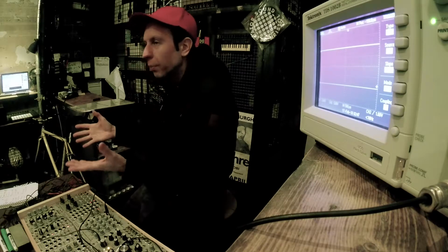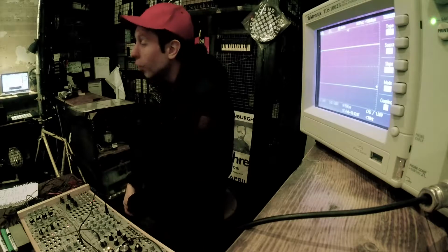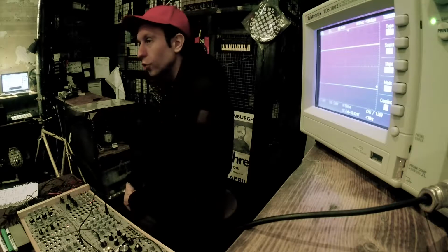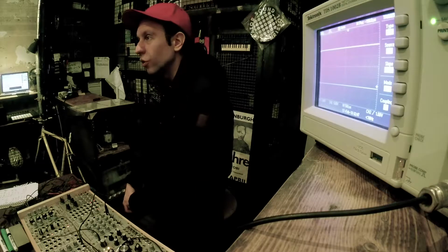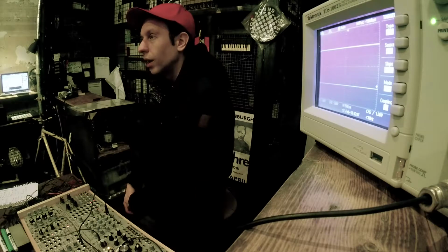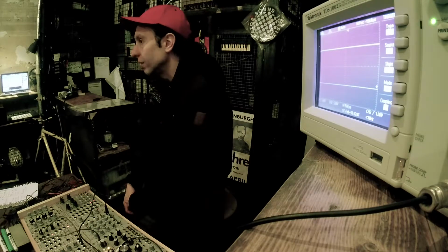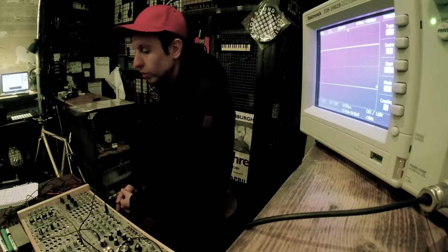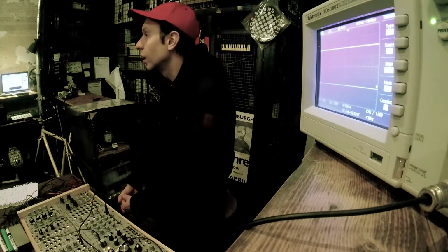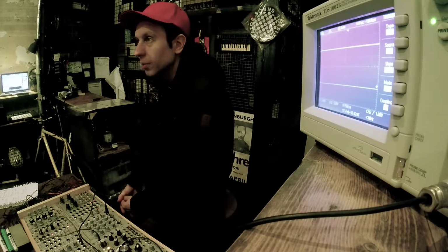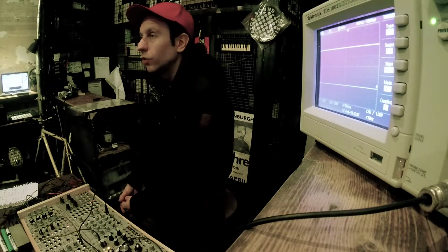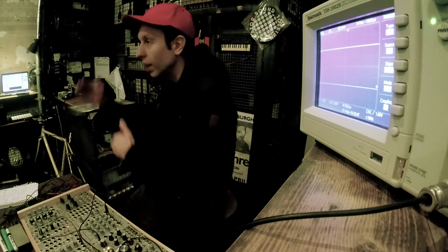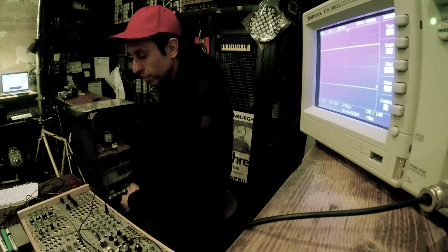So white noise, you probably know, flat spectrum, on a linear scale, not on a log-log scale, so not as we hear it. That's why we have the pink noise, which is flat on a log scale. That's why the pink noise sounds more flat to us than white noise. White noise sounds a bit top-heavy. The point about noise is that it's a broadband signal, and if it's pink noise, it would have equal amount of energy per musical interval, you could say per octave, whereas white noise would have equal amount of energy per hertz. And that's why we have this log-linear scale discrepancy.